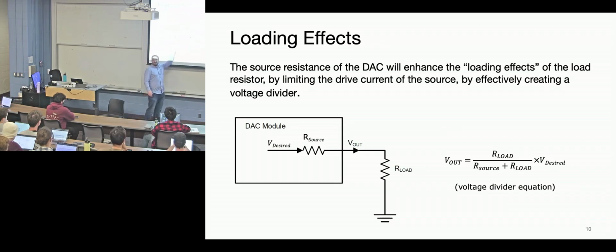And the effect of that is that you have an equivalent of source resistance. Now that source resistance may only be like a couple ohms, maybe 10 ohms, but sometimes it can be more substantial. And the loading here will cause a voltage drop because this is making a voltage divider. Does that answer your question?